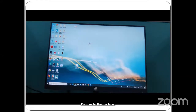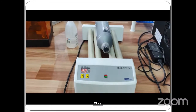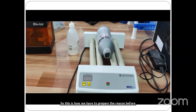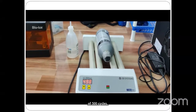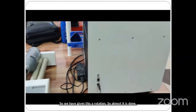So let's say copy. So paste. So this is how we have to prepare the resin before printing. We have to keep the resin bottle in this mixer for 500 cycles. So we have given this rotation, so almost it is done. So now we can use this resin in the printer.